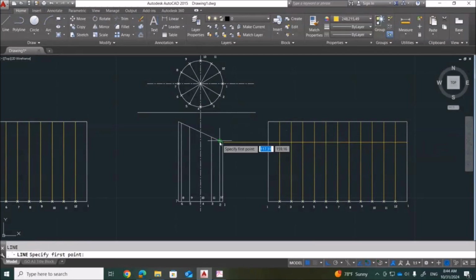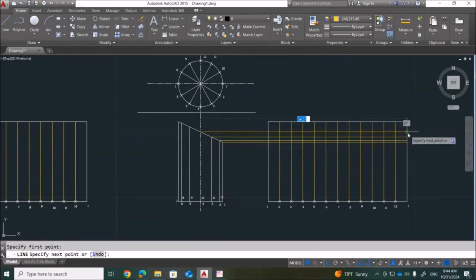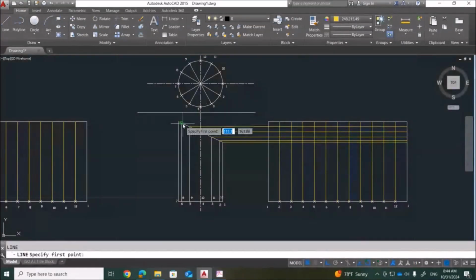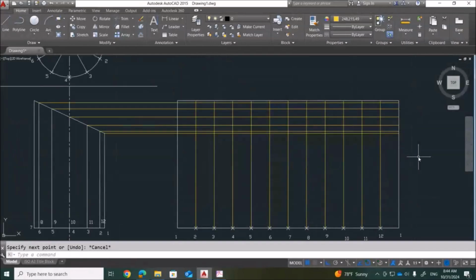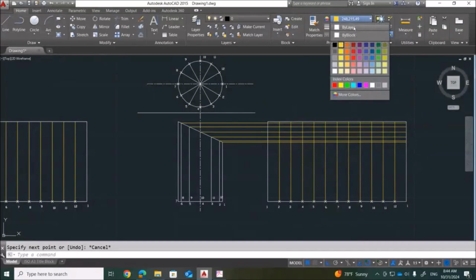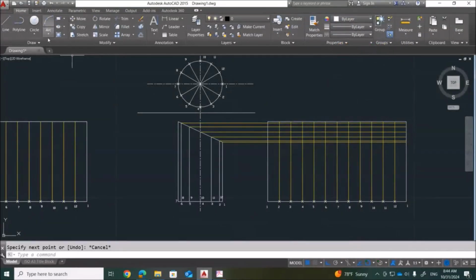Enter from each point. So the same length I will come here. So I can choose here. Enter from this point. Enter center line. There are two lines, so this will not become center line. I will redraw the visible line there. Enter this. Ortho, make it ortho, yes, enter from here, and this line is already here, no need, escape. Okay, so these points, now I need to make them points. I will select the by layer color and now click on point.